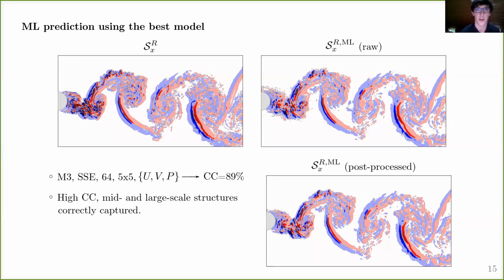And this is some work that we have done already, and we've published a preprint that you can check out if you're interested, where we have this a posteriori analysis, and also we try to assess the generalization of this model to other flow configurations. But the point I wanted to get to is that when we add a noisy prediction in this autoregressive a posteriori setup, this contaminates the resolved quantities in a divergent manner that makes your simulation go completely unphysical.